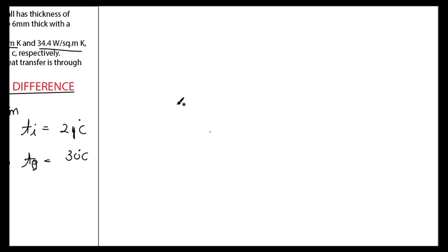Now we know that the U value of the wall is its conductivity divided by its thickness, right? We saw in that earlier formula conductance is equal to conductivity divided by thickness. So it's 0.5 divided by 0.125, which will give me 4 watt per meter square Kelvin. Okay, similarly, so now we have this. Instead of going for this, there is another simple way through which you will understand it better.